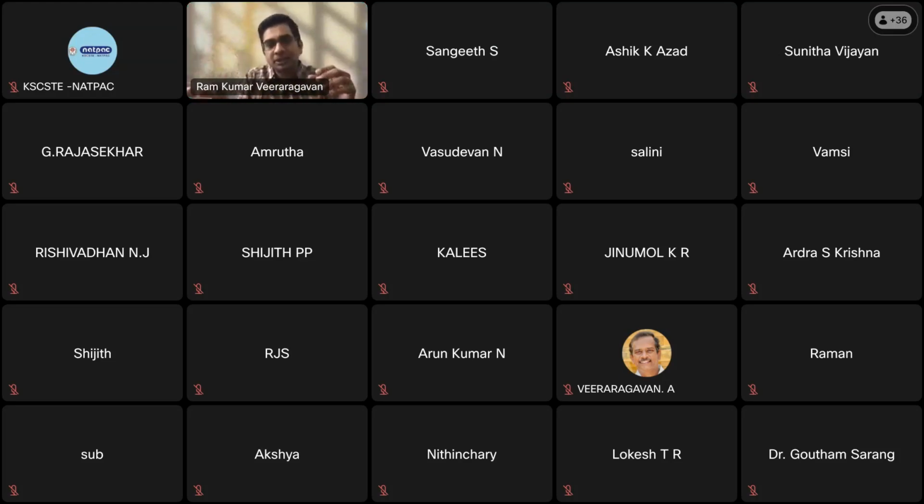Whereas in the neighboring state, like Massachusetts, they have a criterion of 15,000 passes. They felt that based on their previous experience with these mixes, 15,000 is sufficient to address all the rutting issues and stripping potential issues.